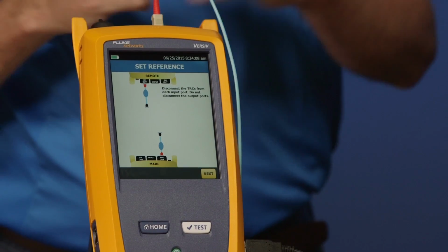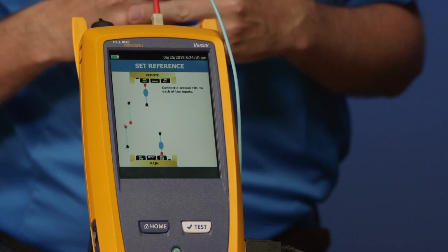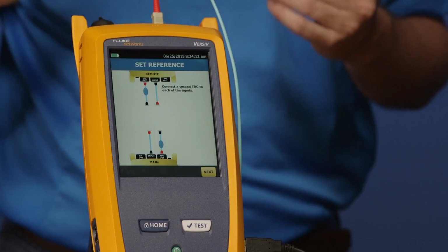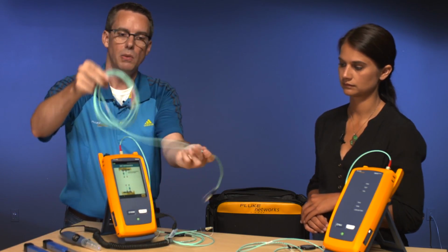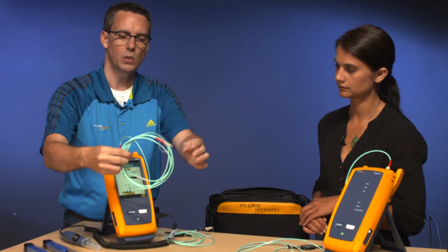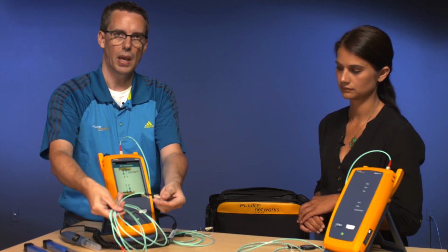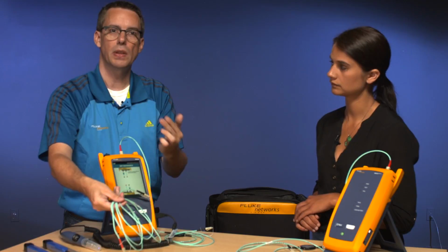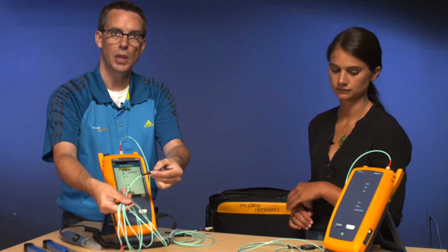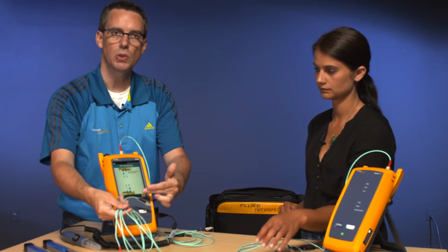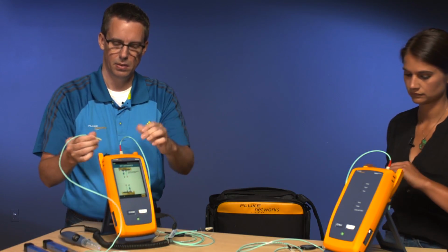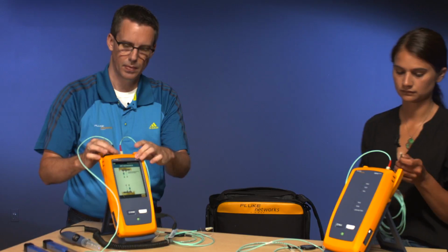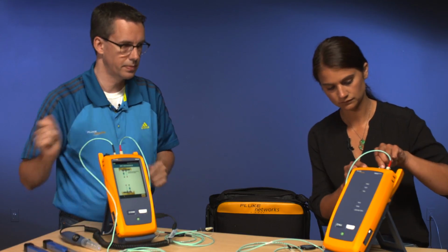Okay, what's next? Go ahead and tap next for me. What's it asking us to do now? It looks like it's asking us to take our other cords and place them in the input ports. Now again, we've got a 50-50 chance of doing this right. One end is red, one end is black. Since it's the input port and that's the code, we'll put the black into the input port. Also noting on the screen here, it's also color coded on the screen. So let's take our black connector, plug it into the input port.